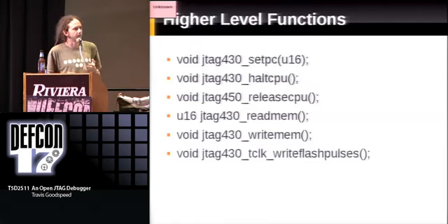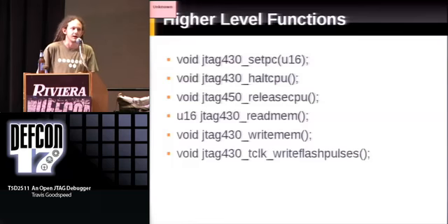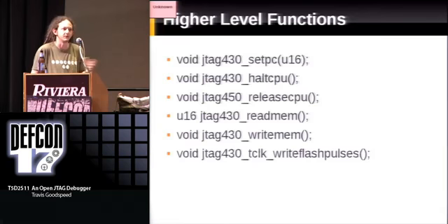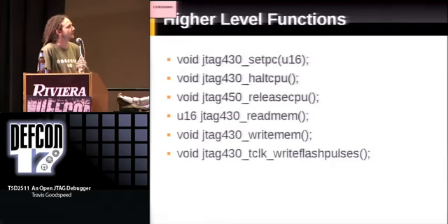I'm sure you're aware that solid-state disks were initially decried as unreliable because flash memory could only be written so many times, and that this is managed by write controllers that actually map the physical blocks of the flash memory to virtual blocks that your PC sees to do wear leveling, so that if you write the same file in the same location a million times, it doesn't destroy the disk. If your timing is wrong when writing flash, you can actually destroy the disk early, which gives you a chance to experiment with exactly how it's destroyed. And I'll get to that in a bit.